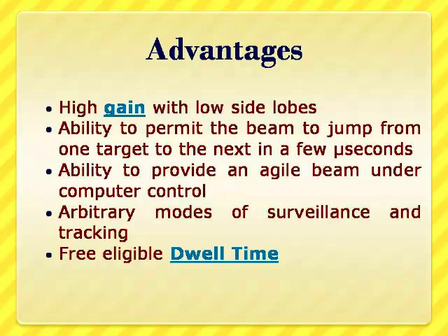You will have some 3 or 4 or 6 pulses to be incident on the target, and the return of those things should be used for processing the data. Changing this dwell time on the target by the antenna system is a difficult task, whereas in a phased array the dwell time can be adjusted very easily because it is all done by electronic means.